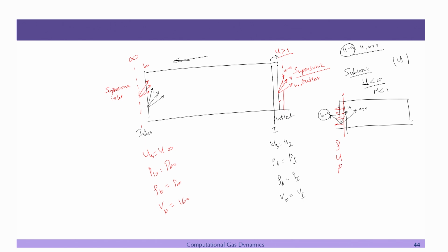So, typically the variable we choose is pressure. Okay. Remember, we have discussed in the last class that both the pressure and velocity cannot be specified. So, we specify pressure, and the other two, rho and u, can be taken from the interior, because there are 2 characteristics which are traveling rightward. Okay. So, you have to give the boundary condition information, and you can take the rho and u from there. Okay. Here, this is the subsonic inlet.